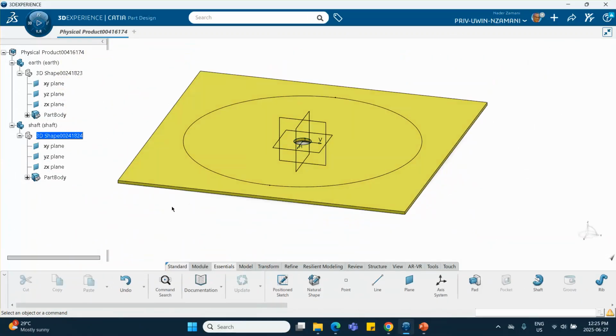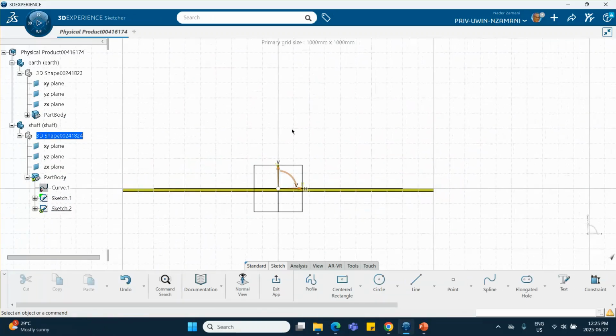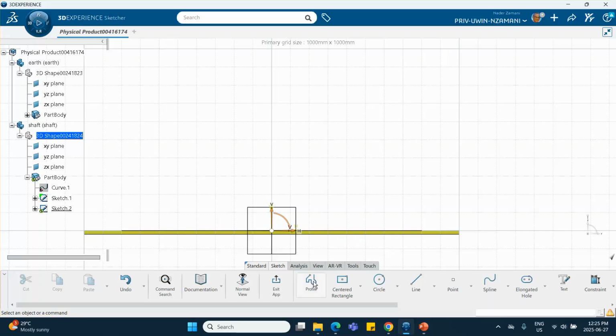Now, because the shaft, I'm going to make it a rib operation. I have the thing that's going to get ribbed or extruded if you want. So it's that circle that I made right there. And then on that vertical plane, I will make the path of that extrusion. So here is how I'm going to do that.